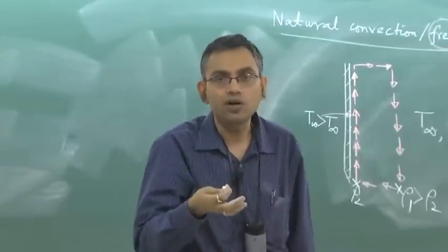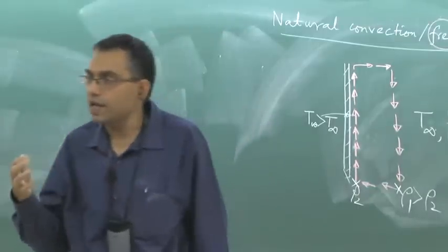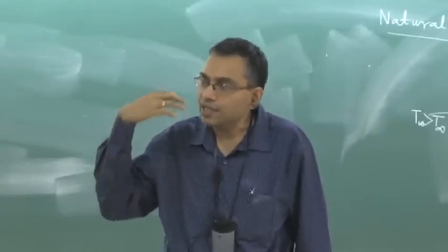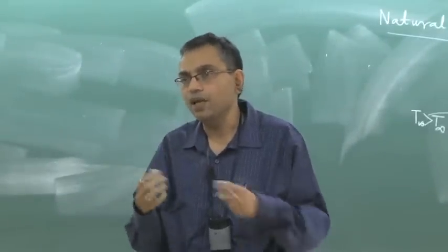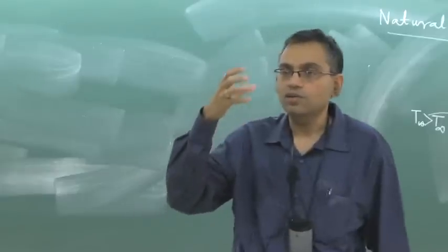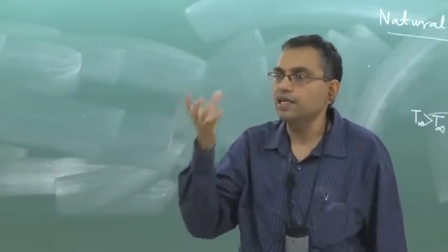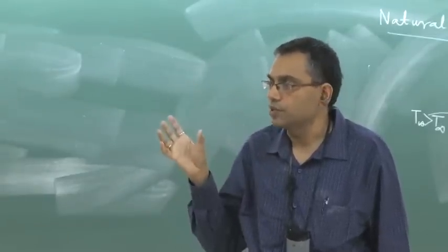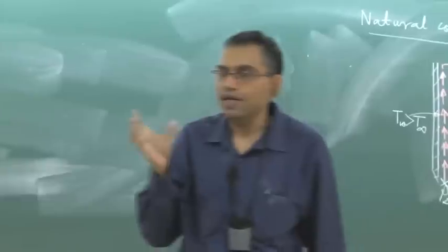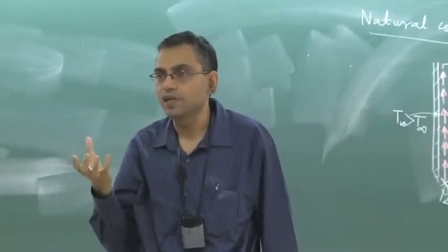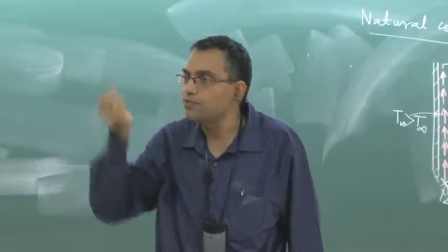the domain. So it is possible that because of temperature gradient there is a density gradient and that drives the flow, but density gradient can be created because of other gradients also. For example, there can be solutal concentration gradient in a multi-component system. So let us say there is a salt water system and the salt water system is freezing.